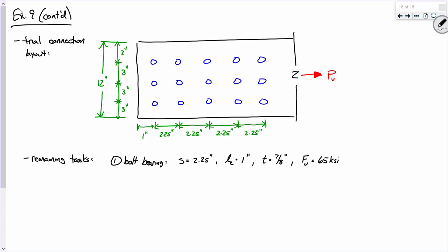All right. Here, I'll sort of bracket all this. So our bolt diameter is 3/4. So you need that to calculate the hole diameter, which to calculate the hole diameter, we take the bolt diameter and we add what? There we go, 1/16 of an inch. Now, the final point I'm going to make is this.